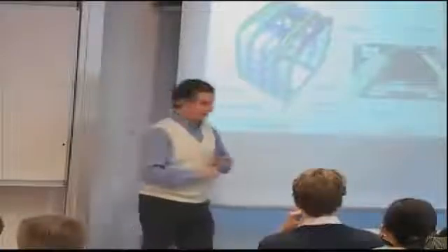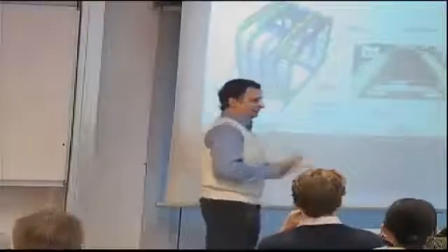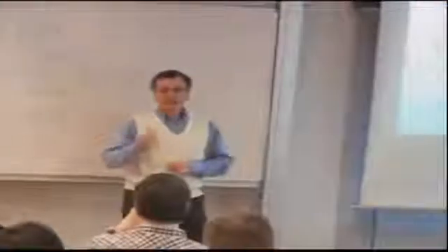Okay, that's what you try to do, and if you do everything, then it's great. If you do even one of them, it's still, in some cases and in some programs, extremely significant, especially the first two, the weight and the cost. So the structures consist of standard parts, and what I want to talk more about is going through some parts and talking about individual failure modes.